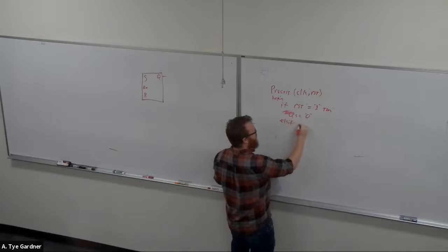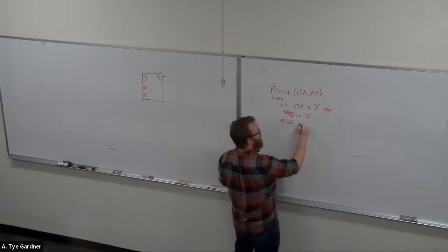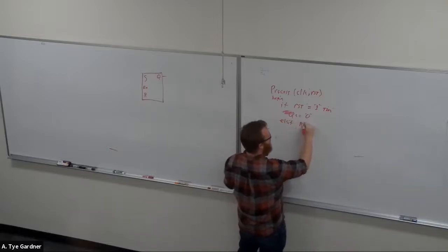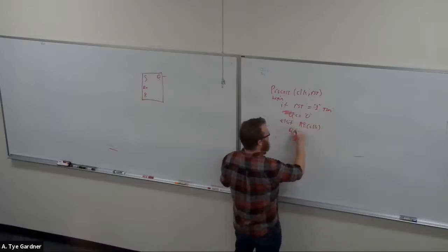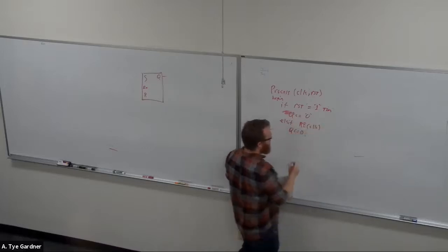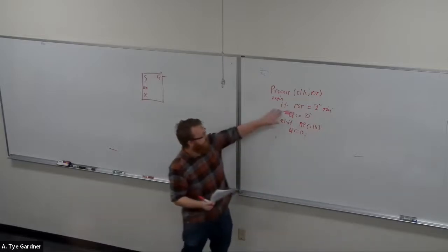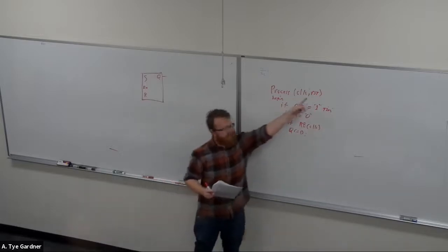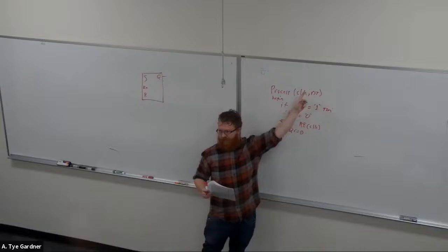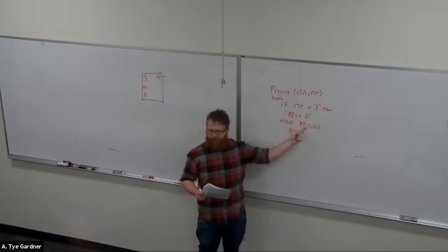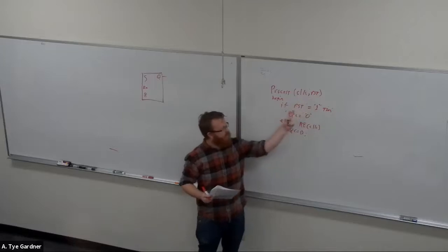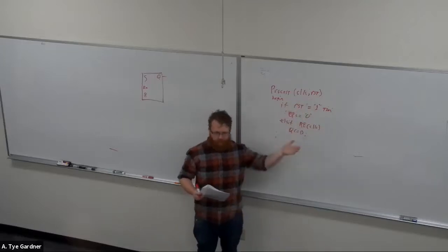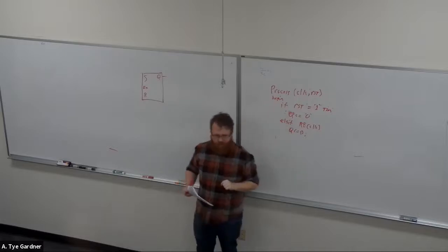Else if rising edge of the clock, Q gets assigned to D. That reset is asynchronous. Yes, that's what I was getting at. So this is an asynchronous reset because it does not depend on the rising edge of the clock to trigger, right? It's in the sensitivity list. Therefore, if it's 1, the process will evaluate, run, determine the if, do the Q.